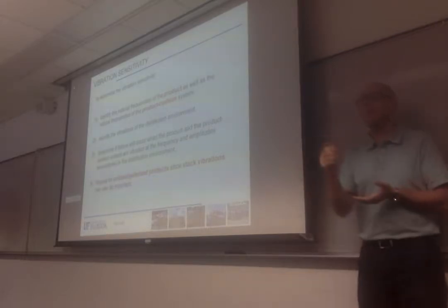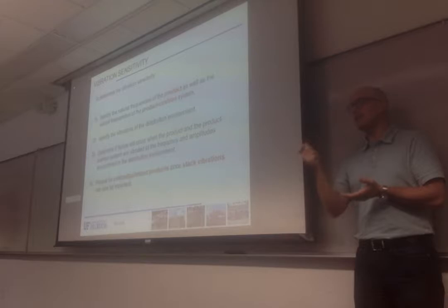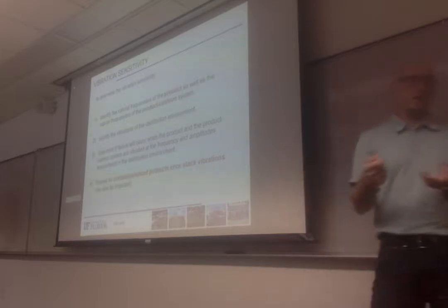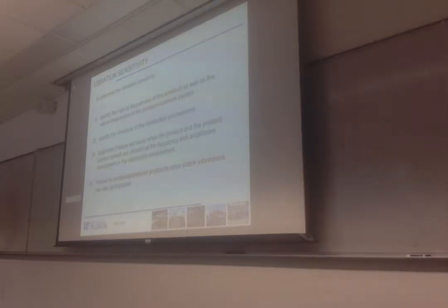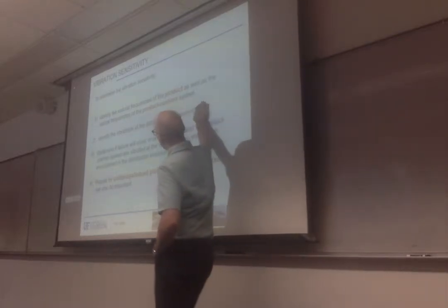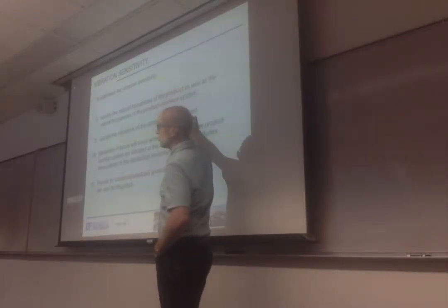Remember that the cushion is there for drops. It's there to protect against impact, not vibration. But as you've seen and as we discussed, because it acts like a spring, it does influence what kind of movement the product is going to see, because of the magnification factor. So look at these two together. Identify the vibration of the distribution environment as well.